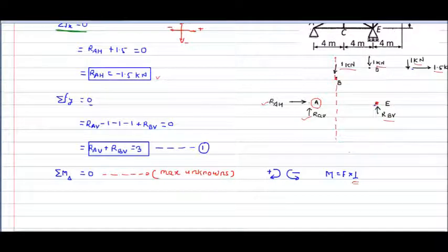You need not draw this line of action. Okay, so first of all, draw this line of action. This is our fixed point, right? So from this fixed point, now draw a perpendicular on this line of action. So if I drop down this line, this will be my perpendicular distance for this force of 1 kilonewton.